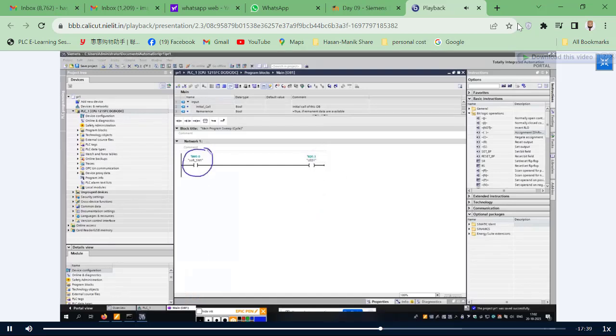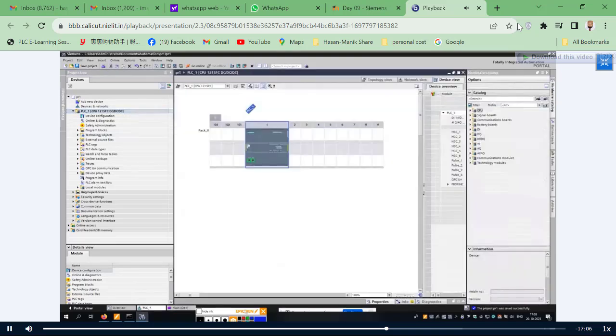So all the information we assigned. This is my soft switch. This is my lamp. Suppose externally, if you want, you can connect a push button. That address we can give. How to give that address? You can give percentage I. There are 14 points, right? Any one of the 14 points where the switch is connected, that address you can give. Understood or not? This is the 0th byte. So a total of 8 switches is 1 byte. The remaining 6 switches are for another byte. That's why that address information is available to the corresponding controller tag.